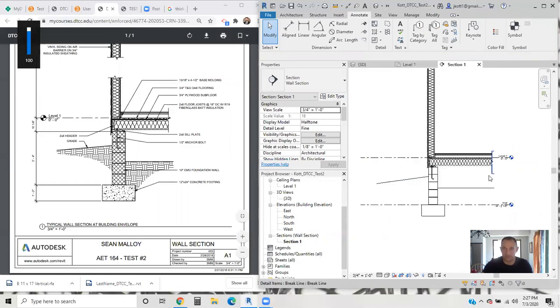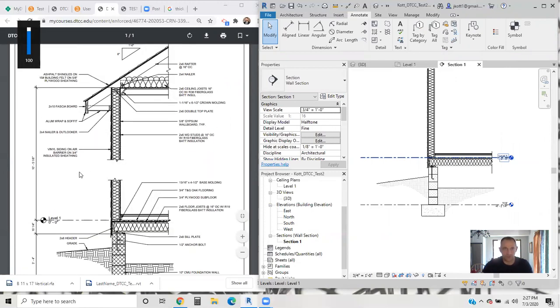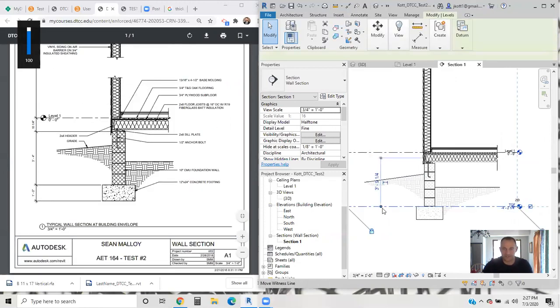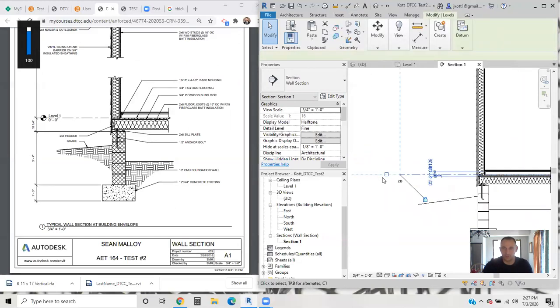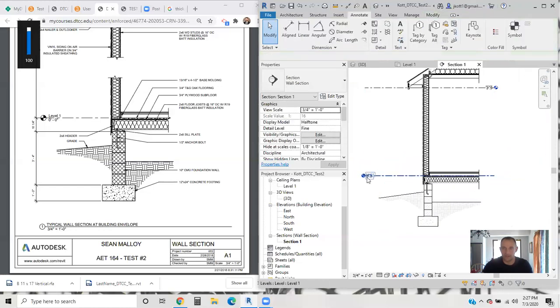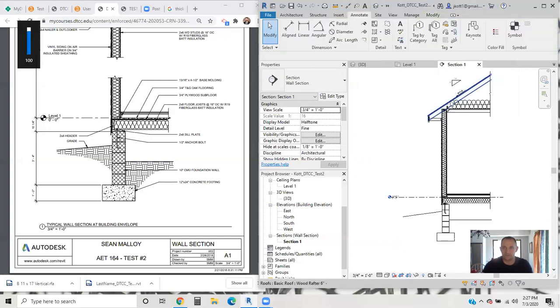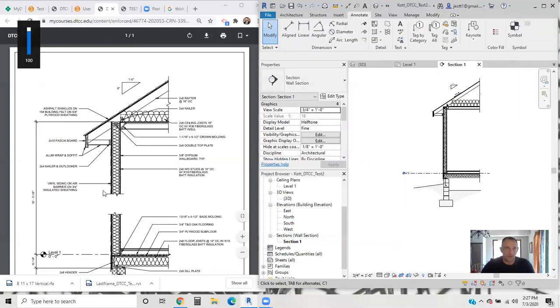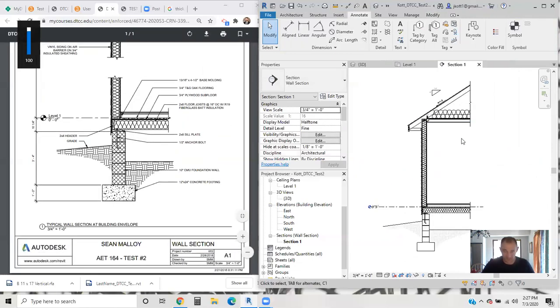Okay, great, we're making great progress here. If you look at the drawings, it looks like they're only showing the level 1 subhead. So we can hide the rest of this stuff. Just click hide, hide element. We want our level 1 marker to be on this side. We can hide them by clicking the checkboxes, and we'll hide the roof tab as well, just so that it's not shown. And now we've got our drawing built out just as we need it to be.